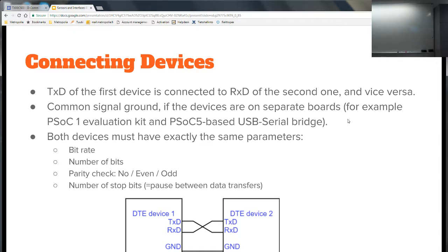Anyways, on this asynchronous data transmission, there are some parameters you have to fix. The most important is the bit rate. Without the bit rate fixed, you cannot see much of data transmission happening, only funny bits showing up. How many data bits? That's also something you need to fix. The most common is 8 bits.